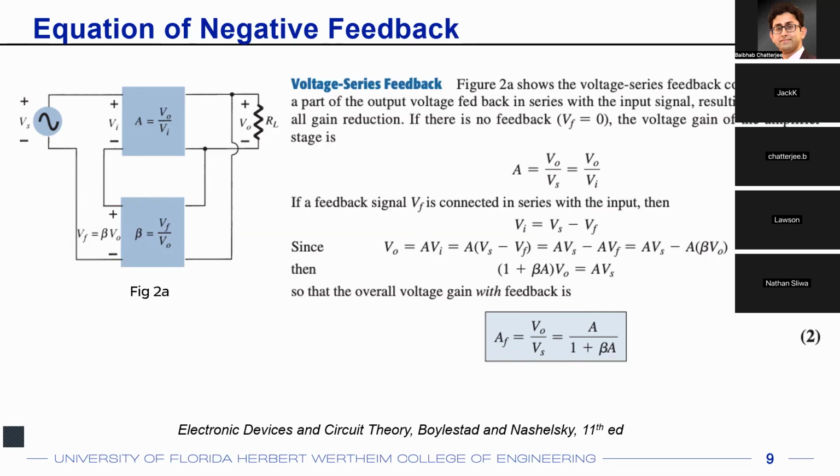So you have to design circuits with it, but you can, let's say, model this entire complex op amp with a gain of A, and that could become your black box. But your question is valid, because inside this black box there could be a complex circuit. There could be an op amp, there could be multiple resistances going in and out. The same can happen with beta and so on. But in the simplest form, this is how the equation for feedback looks. Inside A, there could be 100 different circuits. Inside beta, there could again be 100 different circuits.